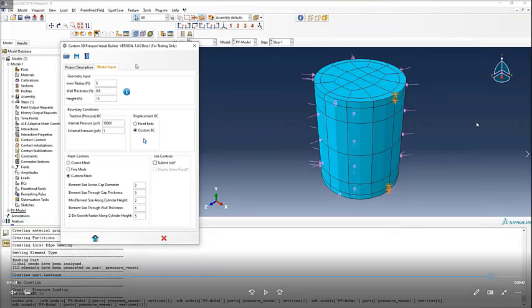I'm not sure I quite understand the question by batch. I think I'm kind of understanding it. Other than using a batch file, what I can say is that in the script, you can mention to run one job after the other. So yeah, I think it is possible. And also, as I had discussed when I was showing Isight, you can embed this type of system within Isight, and then it can automate the job submission for you by making the changes in the boundary conditions. So you do not necessarily have to run a batch file. You can automate this process within Isight.